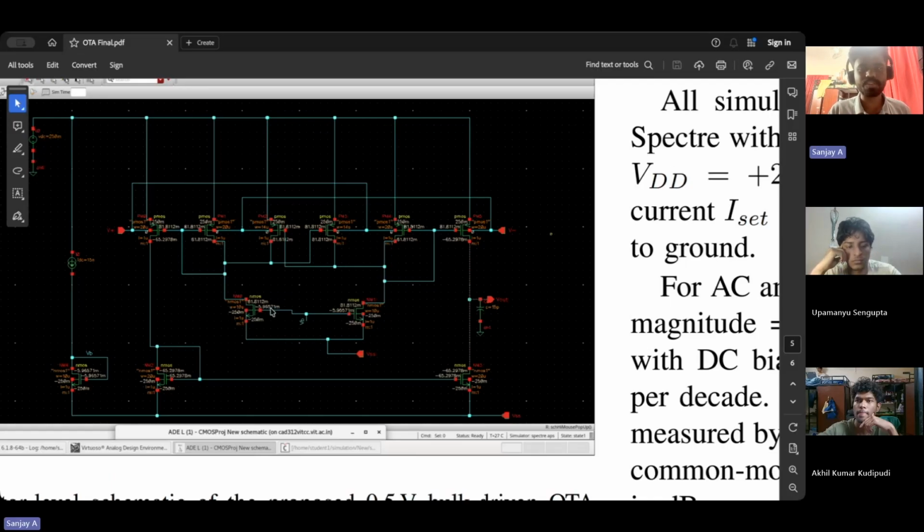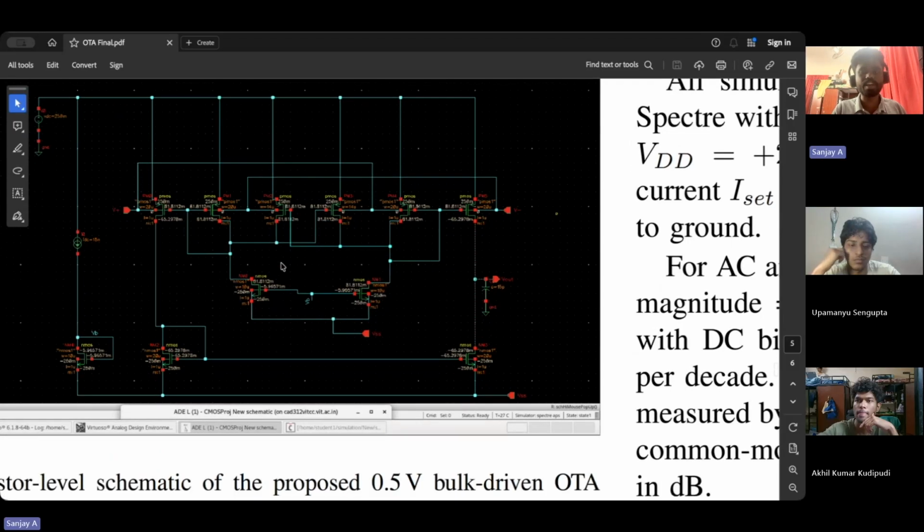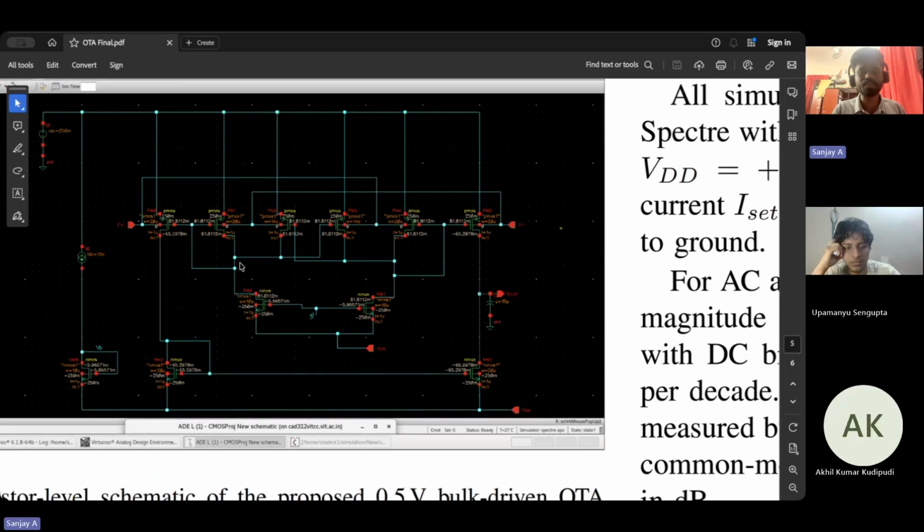This is the heart of the circuit that makes the design actually work. Let me be very precise here. The fundamental problem with bulk-driven operation is that GMB will be approximately equal to 10 to 20% of GM. So the transconductance of our input stage is roughly 5 to 10 times lower than a gate-driven equivalent. This directly reduces voltage gain.